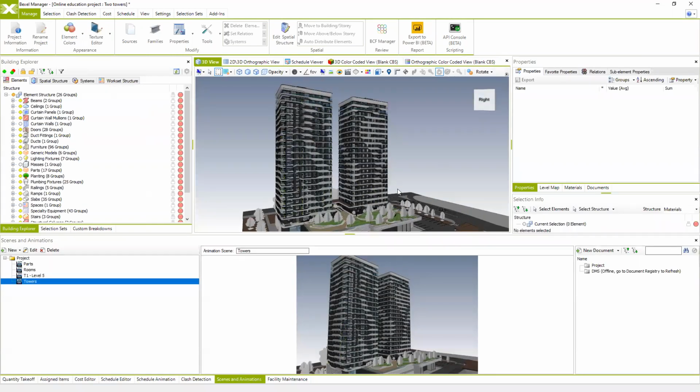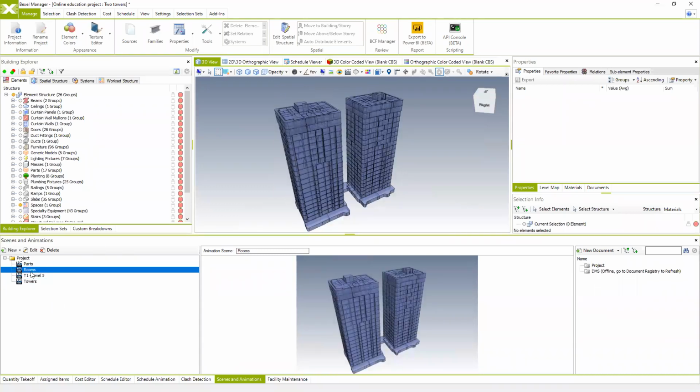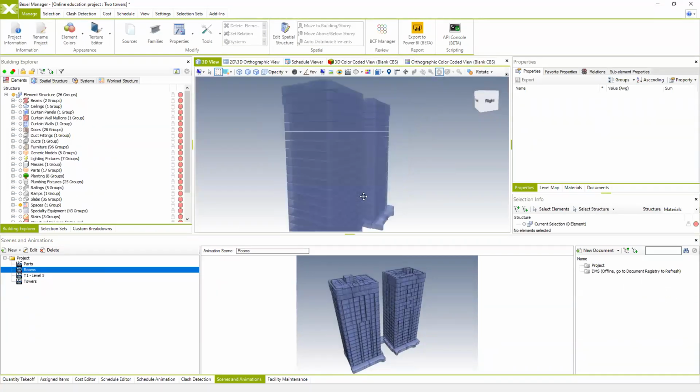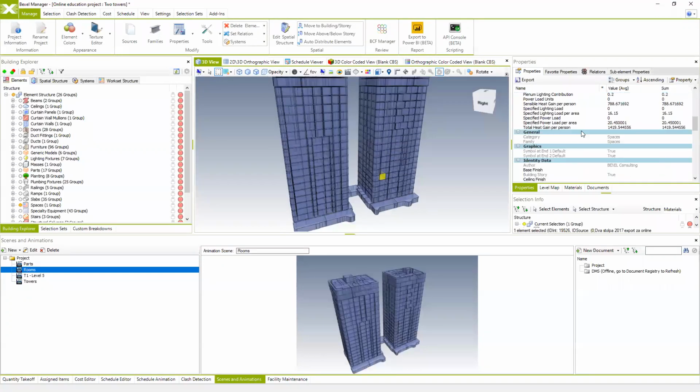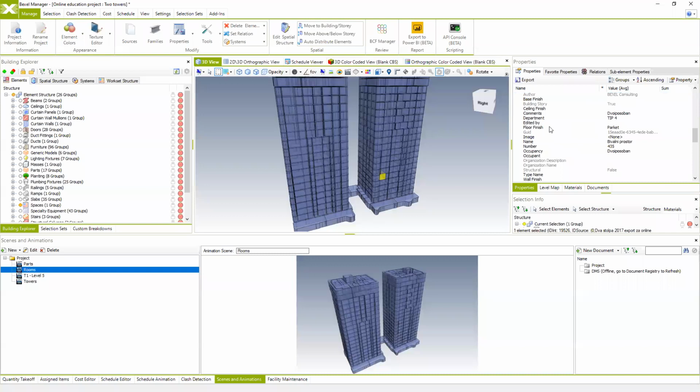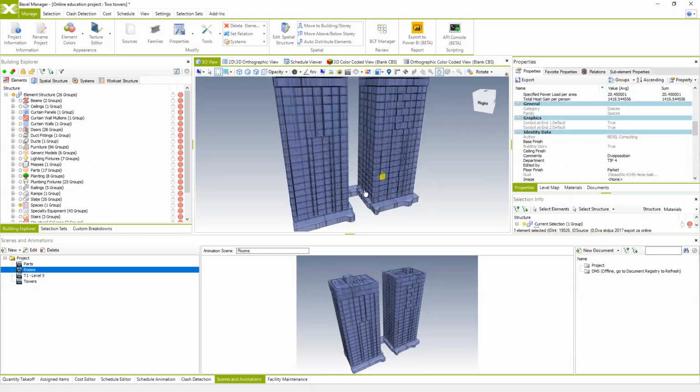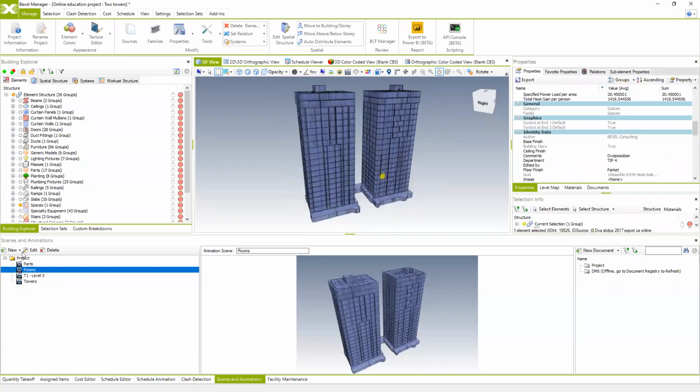And here I'm going to present how you can create quantity takeoffs for, let's say, the rooms using different properties available. In this case, I'm going to use already created scenes. And now you see all the rooms in our buildings, and each room has specific properties. And if we want to include information regarding types of the rooms, number of the rooms, description, and the names of specific elements, in this case rooms, but you can choose any property from your BIM project, we can create a quantity takeoff.